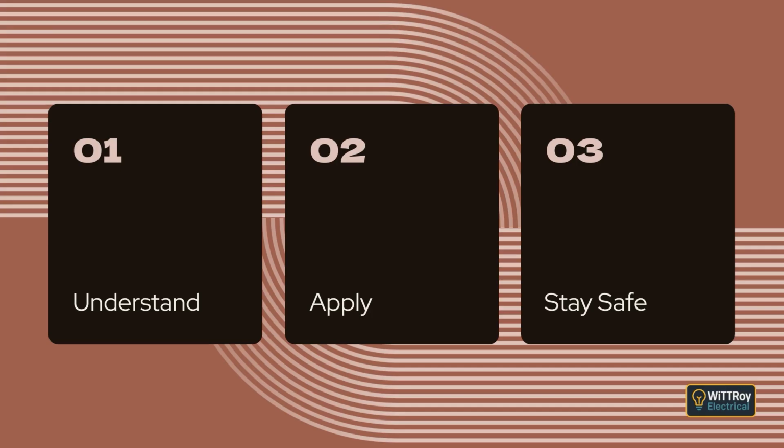This includes a clear working space of at least 0.6 meters in front of the switchboard, an alternative exit path if the switchboard is longer than 3 meters, or if the fault current is high, or if the installation needs 2 escape routes. Doorways must be at least 0.75 meters wide and 1.98 meters high to allow safe entry and exit. Switchroom doors must open in the direction of escape and must be able to open without a key or tool.